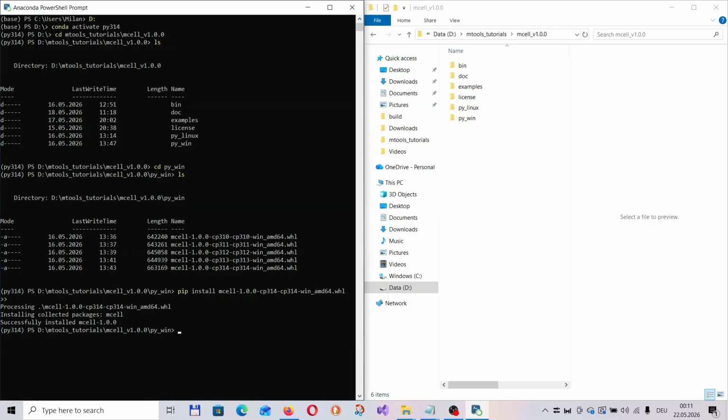The first step is to determine the host ID for your machine. This can be done in two ways. One way is to use the executable file mhostid. You can find this file in the license folder you obtain after unpacking MCell.